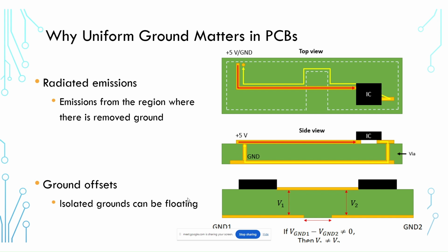And this occurs when you have two floating grounds. And that's exactly what you get when you take a PCB like this, and then you split it into a digital region and an analog region, and you have them totally disconnected. So you don't have this small section here to couple the return currents. So when you have those isolated floating grounds, and then you try to route a signal over them, you get the same situation as we saw before, which was strong radiated emissions.